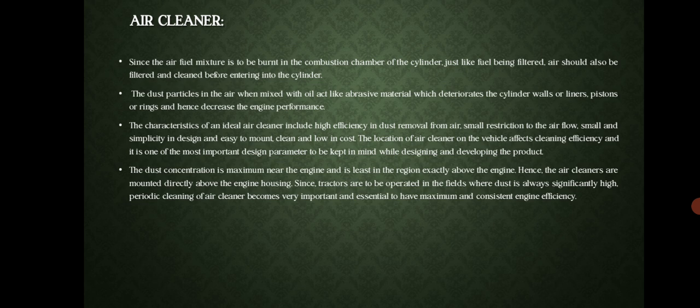The dust concentration is maximum near the engine and is least in the region exactly above the engine. Hence, the air cleaners are mounted directly above the engine housing. Since tractors are operated in the field where dust is always significantly high, periodic cleaning of the air cleaner becomes very important and essential to have maximum and consistent engine efficiency.